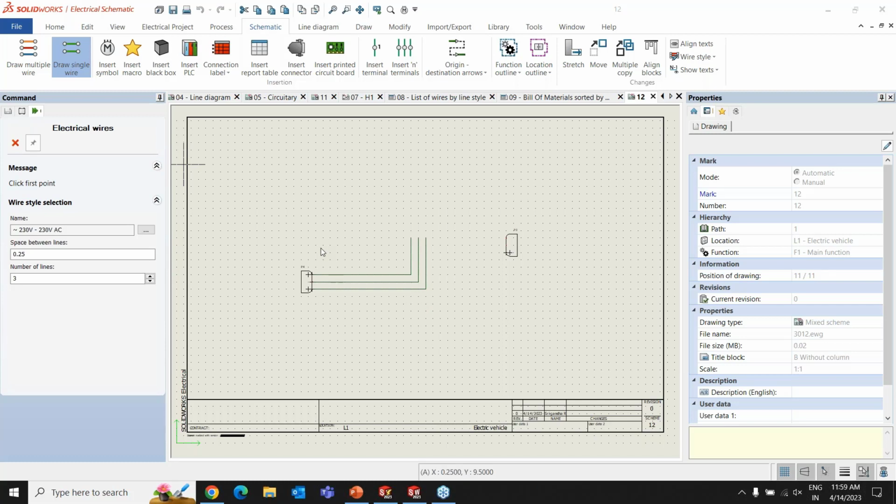Okay, so Rajita ma'am is asking, suppose we have a step file of a PCB placed in an enclosure which has connectors as part of the PCB, can we use SolidWorks Electrical for automatic routing? Yes, if that particular step file is compatible with SolidWorks, you can surely take that part and turn it into an electrical component. Like I told, you can give some intelligence to it and do the routing. But the schematics has to be done in SolidWorks Electrical itself. Then you can easily go for routing the same components, just like how I have shown.